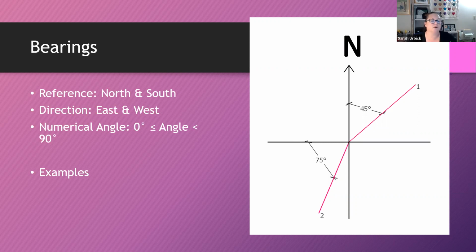All right. So if I have an angle and I'm starting from true north, from straight north, and I go 95 degrees to the right, where does that put me? Now I'm facing east, but since I'm over that 90-degree mark, now I'm really in that southeast quadrant. I'm down in this area here. So that's one of the things we're going to watch out for: where does my angular measurement take me and what direction am I facing?